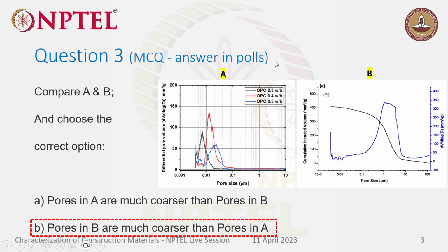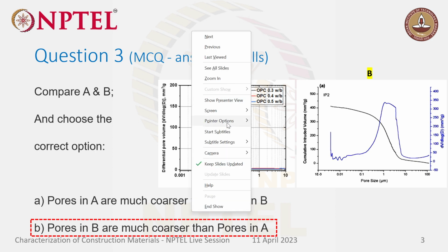So, sir, I've mentioned lime plasters, which are used for historic mortars with which the historic buildings have been constructed. The pore sizes are coarser in lime plaster because they have more breathing capability, but when you compare a cement system, it doesn't have that breathability because the pore sizes are very fine, and that kind of breathability will not be expected from a cement system. Okay, let me take the pointer.